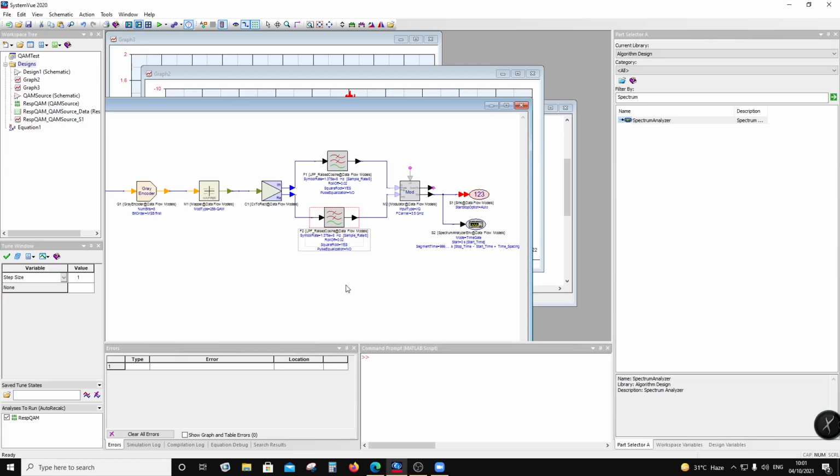Once you receive it and you separate the subchannels, right, then there is a lot of correlated information between subcarriers, and that correlated information is the channel estimation or the noise, stuff like that. So you do not have to have an explicit channel estimation here.